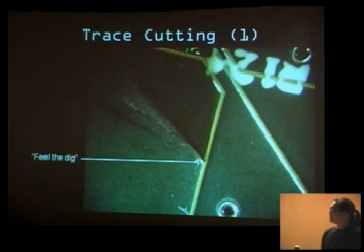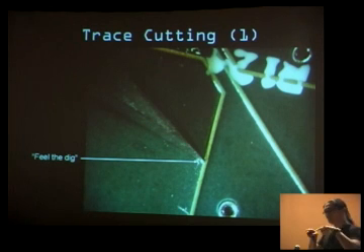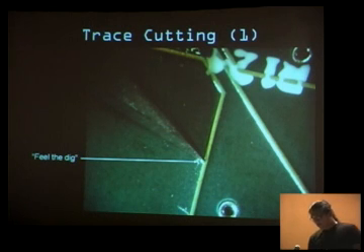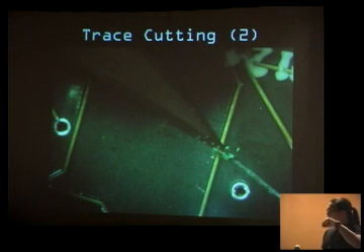When you want to cut a trace, here's this through a microscope. This is the tip of an X-Acto razor blade. What you do is you take the knife and slide it up to the edge of the trace. The trace is actually slightly above the level of the circuit board. When you slide up the trace, you'll feel a dig, a kind of catch, right? Once you feel the dig, you keep on pushing until it goes past, and then you roll the blade back.